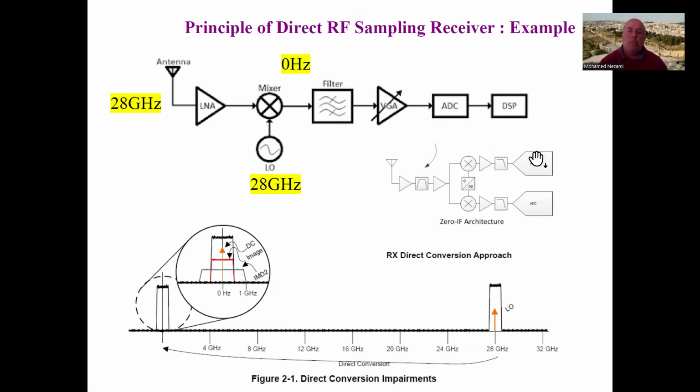And you get the complex stream, which is the I and Q in here. But when you combine these to create the baseband signal, you're going to get a whole bunch of issues when you directly digitize the zero IF or near zero IF that you're creating from the incoming modulated carrier by direct conversion. Okay, and that's illustrated in this figure in here.